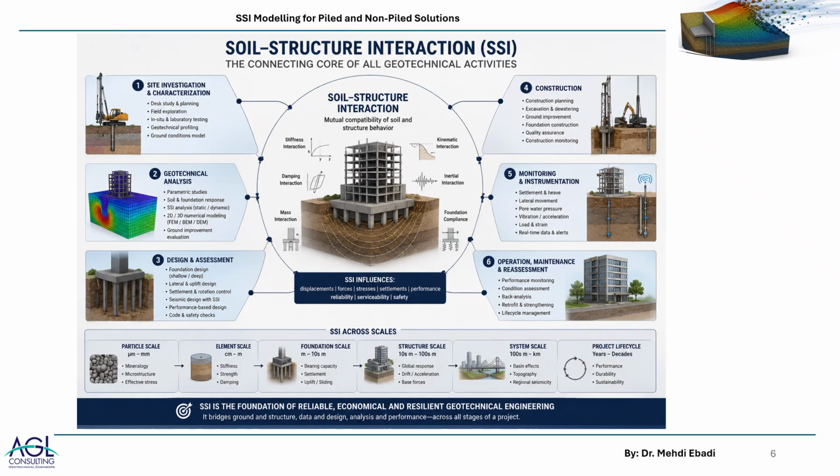A model that we do in soil structure interaction, or in general in finite element modeling, includes micro level, which is like particle size level, then element scale level, which the mesh size would be the governing parameter for. Then foundation scale, which is the arrangement and what has been designed or will be optimized by our analysis.